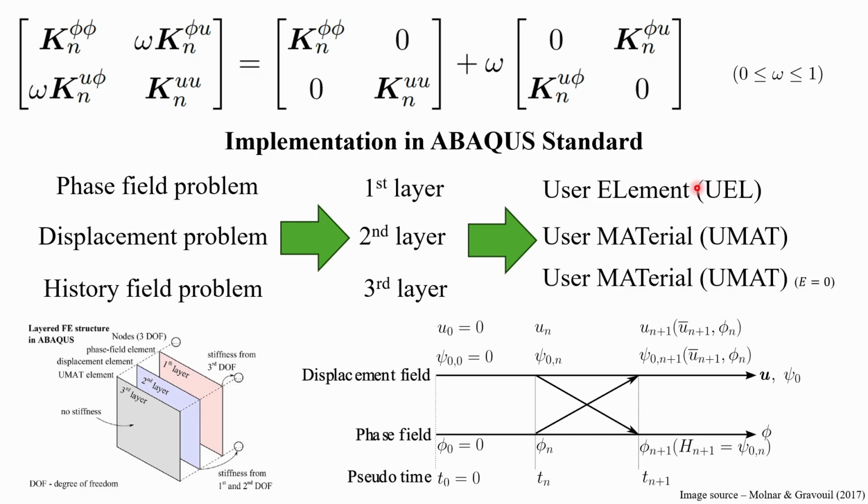Again, there are many methods available. Suppose you don't put omega equals 0. You have omega equals 1. So essentially what do you have? You have this entire stiffness matrix, right? This can also be inverted in order to calculate phi and u. And that is a monolithic formulation. So you are solving the entire coupled problem as it is. You are not decoupling it. Of course, computations will be very expensive, but your answers will be a little bit more accurate, like your force displacement responses.